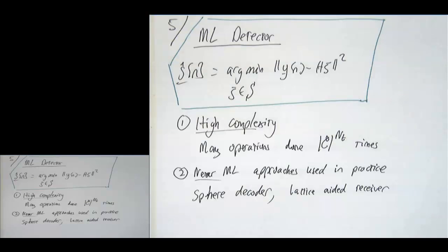In actual practice, how many antennas are generally used? In most systems right now, it's up to 4 typically. So 4 transmit and receive. That would be for a better implementation in 802.11ac. In cellular, the mobile often has 2 receive antennas, so you could have 4 at the transmitter.